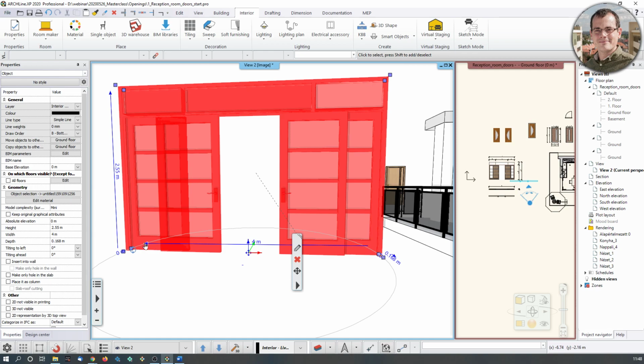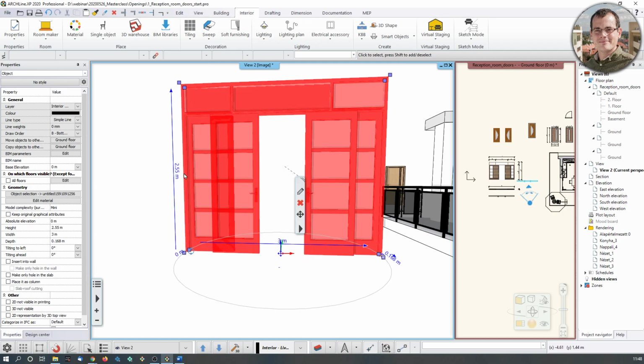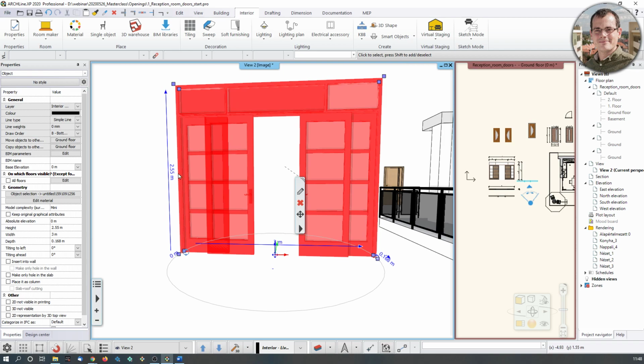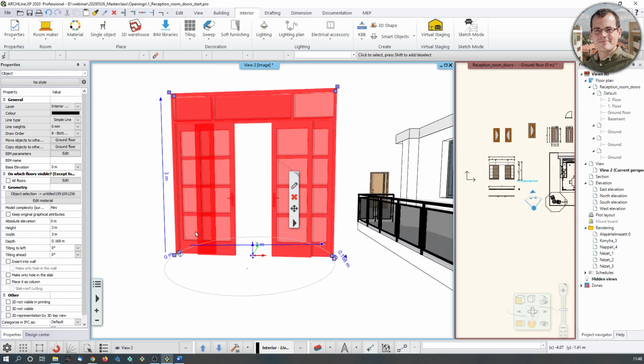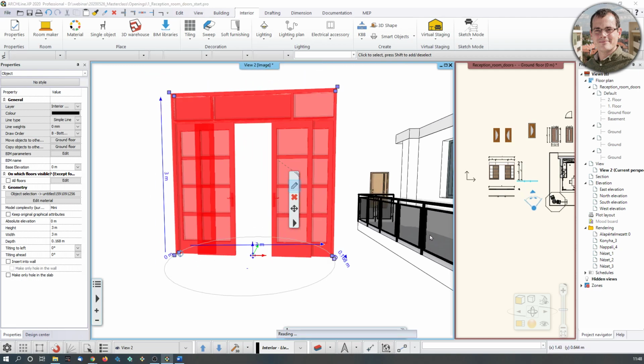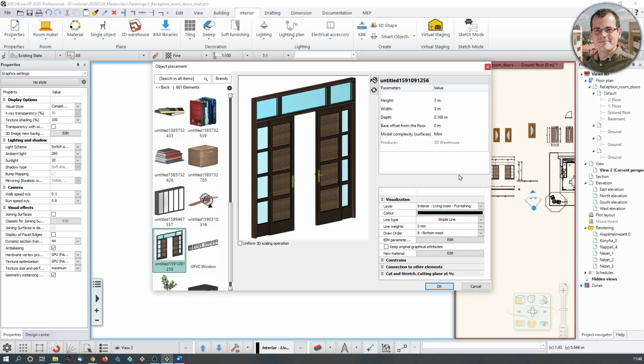If you click on the arrowheads, that's the way the software is going to move the endpoint. So if you now decrease this back to 3 meters, then the endpoint is going to be snapped closer. Let me just hit enter, and you see this is how you can govern it. If I change the size to 3 meters, then this point is going to move upwards and not this point moving downwards, if you know what I'm getting at. So that is what you're looking for. If you want to resize something, you can do that also here.